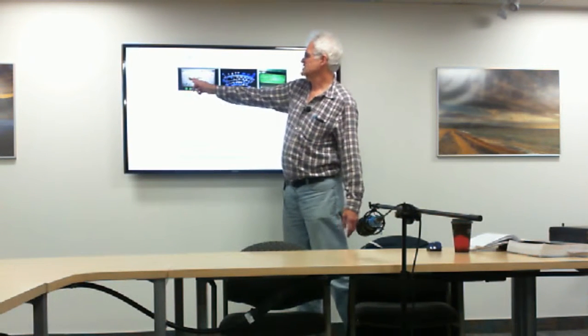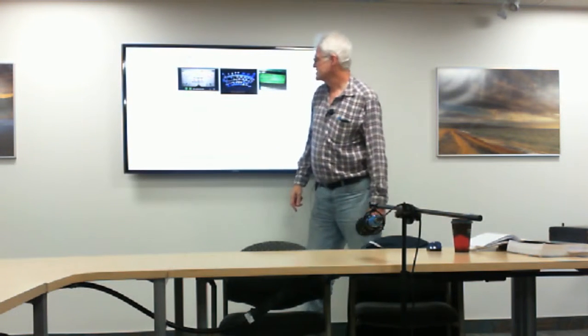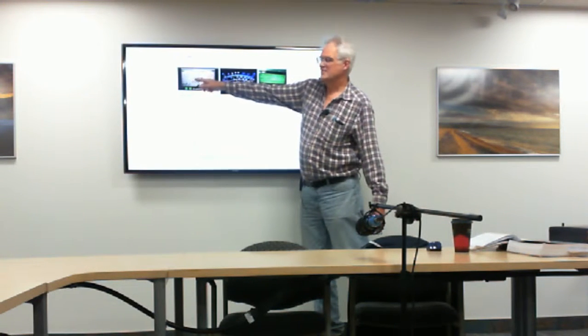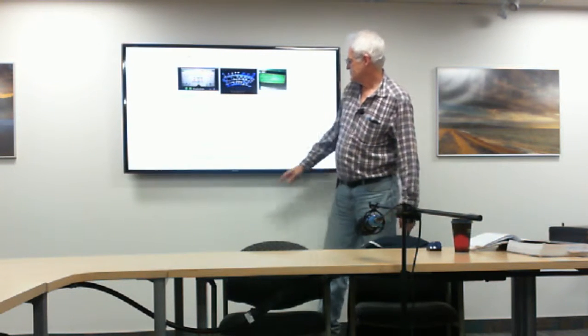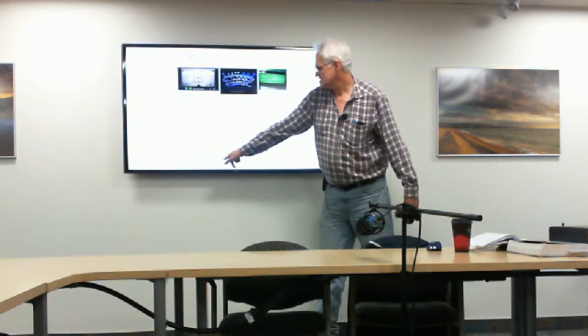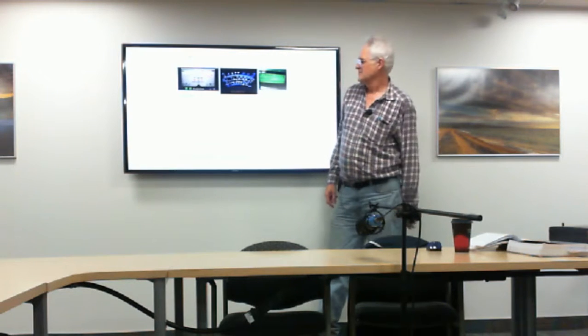So you'll get signals typically on HF from 0 to 9. When you have really good signals, they'll get into decibels, so you'll say S9 plus 20, S9 plus 30. For example, 30 decibels is 1,000 times more signal than S9. We don't need to get into the math of that, but the decibel scale is just a scale of representation.